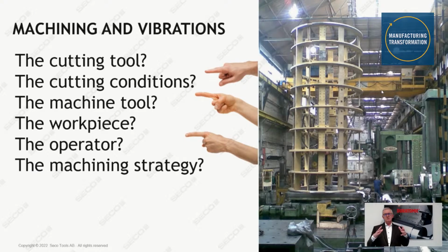Because you have to see machining as a machine tool and a workpiece fixed on the machine tool, and a cutting tool used with certain cutting conditions, and a cutting strategy. How do you move the tool over or in the workpiece? All these things together form a dynamic system. And each element there can be the main reason, the source of vibrations.